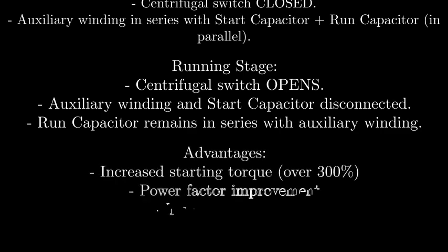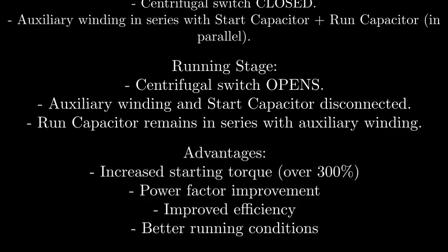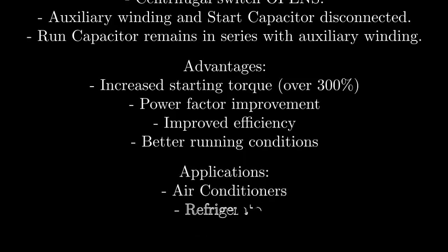This clever design offers significant advantages: an increased starting torque of over 300% of the full load torque, improved power factor, enhanced efficiency, and overall better running conditions. Consequently, these motors are used in heavy-duty applications like air conditioners, refrigerators, and compressors, where both high starting and running torques are essential. We have now seen how 2 capacitors enable the highest performance.